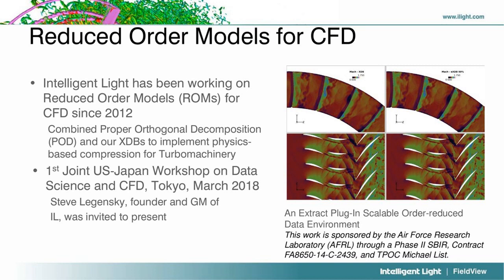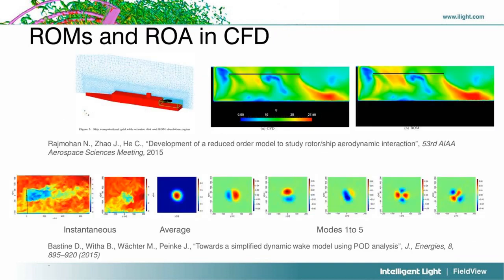So why is that interesting for CFD practitioners? What are the benefits of modal analysis in general? You can see a few applications here on this slide, but basically it comes down to what you can do with this approach. Modal analysis allows you to build, as the name says, reduced models. So if you have complex flows, or very long unsteady simulations, you can obtain a model that is smaller and lighter to use, and you can use that for further simulations or further computations.